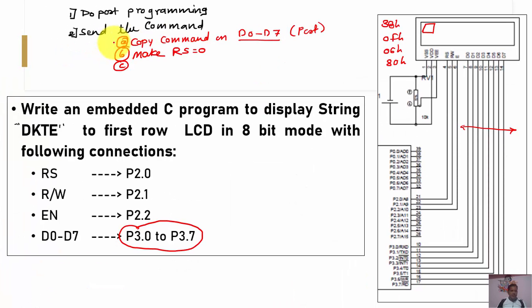Okay, so as this is an output device, we are going to send data on this LCD, which means we are going to write the data on the LCD, and for that make this R/W bar pin equal to 0. And at the last, in order to enable the LCD, simply make EN 1 first, give some delay, and make it 0 again. So what will happen? One high to low transition to send this command, right?